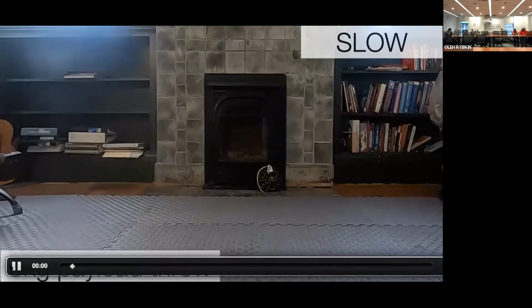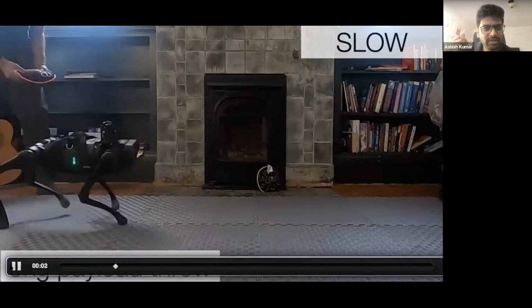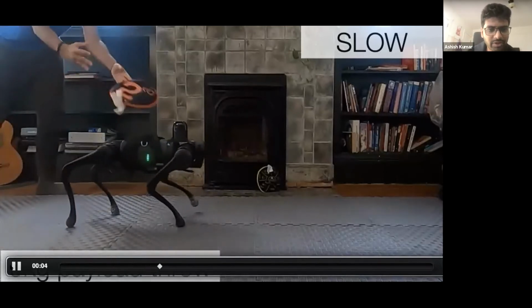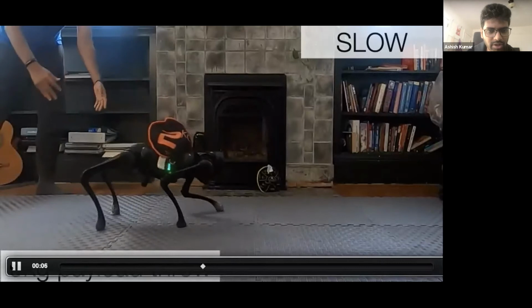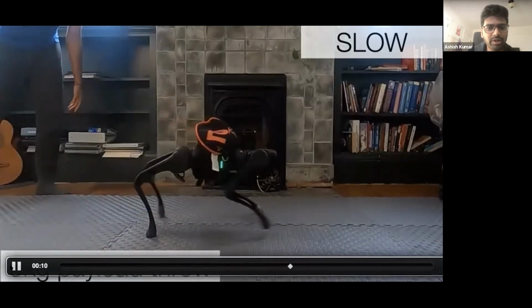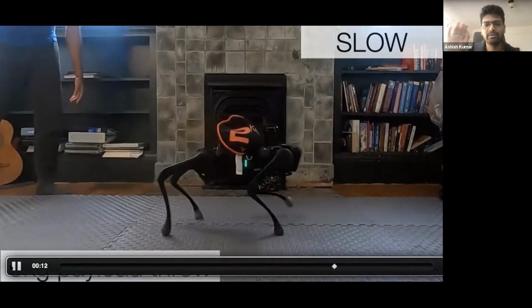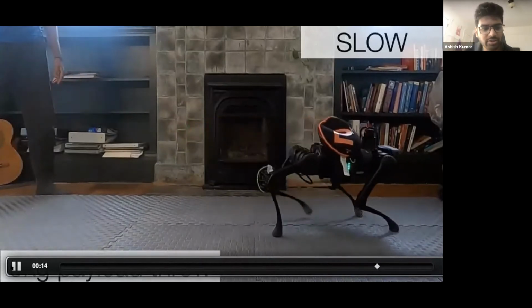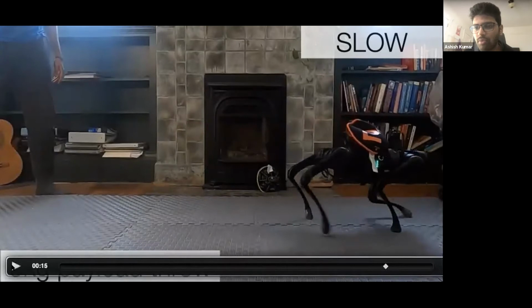So there is some very small latency. If you look at this, when we throw this payload on the back of the robot, it sags for a small amount of time before it goes back up and recovers its behavior. So there is a very small amount of adaptation time, because there are two things. First of all, the history should have enough information to predict, because if the payload lands, it's probably not enough to estimate what happened by just looking at one time step.